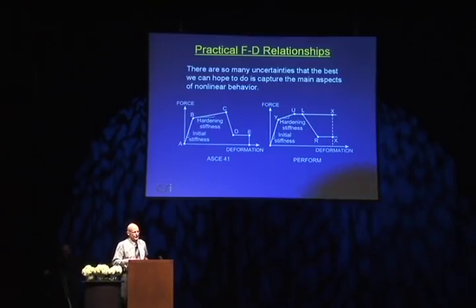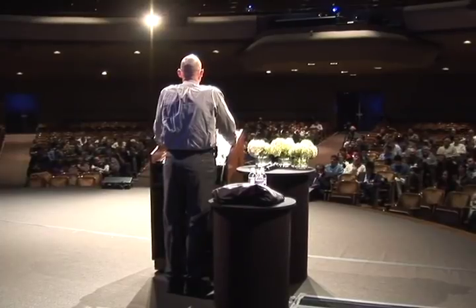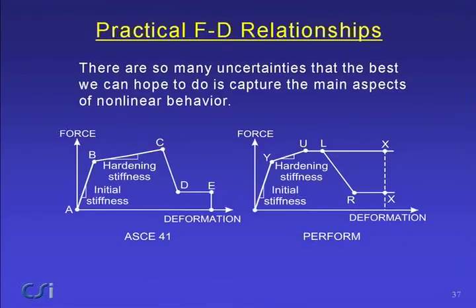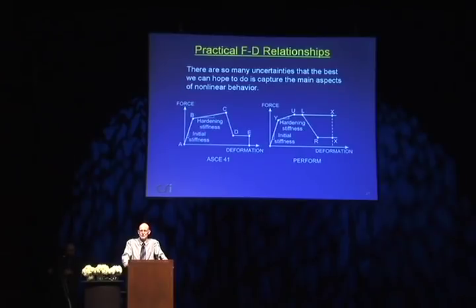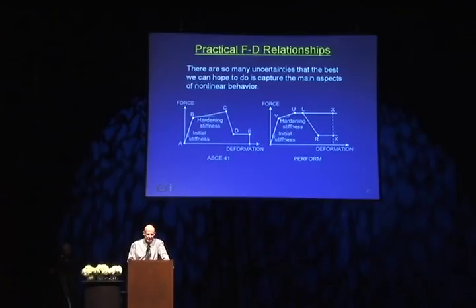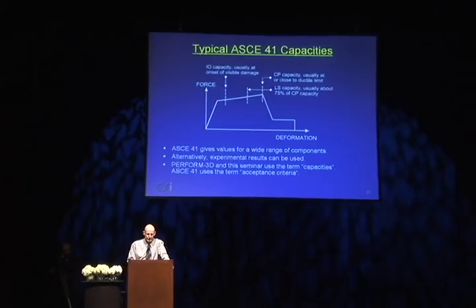And point X out here, typically you'll specify that to be some fairly large value, such that if you ever get out that far, you'll say, well, something has gone wrong or the structure isn't right. There really isn't any point in continuing beyond point X. So if this was, say, plastic hinge rotation and point X were 5% hinge rotation, if you've got that much hinge rotation, there's no point really in continuing the analysis, you may as well stop. That is what Perform uses the X point for, mainly, to stop the analysis in case you get deformations which are unrealistically large.